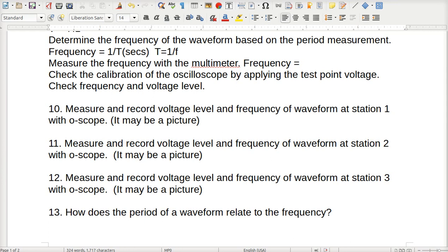When you look at a picture, I don't care what voltage level you give me because I didn't ask for it in a specific form. So if you give me peak voltage, make sure you write it down as peak voltage. If you give me the peak to peak voltage, make sure you say it's peak to peak. If you want to calculate the RMS voltage and just put down V, then you better be giving me the RMS value for that waveform, which you can't see directly.